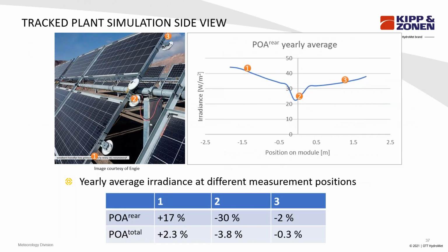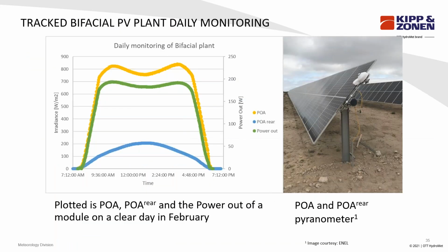You can, in the simulation software, choose how you model the module and the plant, and then you can also select what the torque tube would look like, and it influences whether you have this dip, yes or no. And it is nice that the builders of this software have allowed users of the software to configure this and to model it in order to best simulate the plant they have. So it's an option that can be chosen.